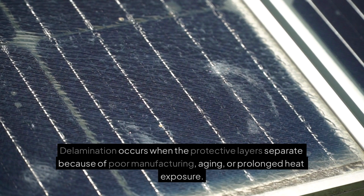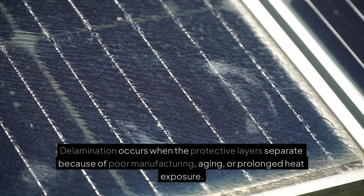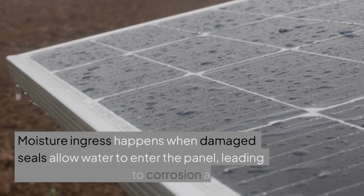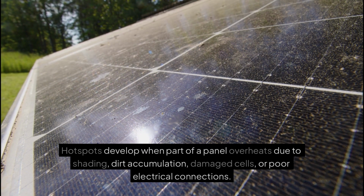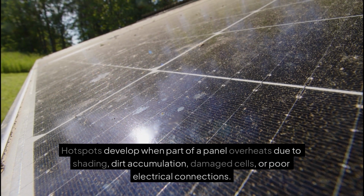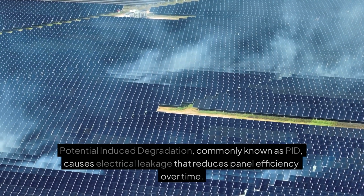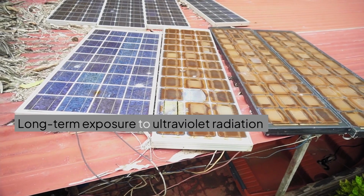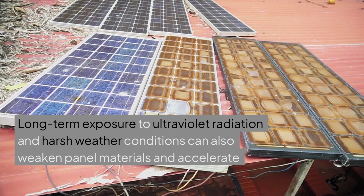Delamination occurs when the protective layers separate because of poor manufacturing, aging, or prolonged heat exposure. Moisture ingress happens when damaged seals allow water to enter the panel, leading to corrosion and electrical failure. Hotspots develop when part of a panel overheats due to shading, dirt accumulation, damaged cells, or poor electrical connections. Potential induced degradation, commonly known as PID, causes electrical leakage that reduces panel efficiency over time. Long-term exposure to ultraviolet radiation and harsh weather conditions can also weaken panel materials and accelerate aging.